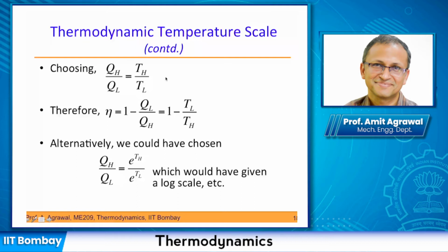Sir, we are using this Carnot cycle for calibrating the temperature, but what were we using the ideal gas thermometer for? Further, we are going to define a temperature scale right now, and then we are going to measure the temperatures using this temperature scale. We need to have both things. We need a scale against which we are going to measure. We are defining things first, but unless and until we can measure it, it is of no use. Practically we can never use it unless you can actually calculate things or do things. So we are actually measuring things using this ideal gas thermometer.